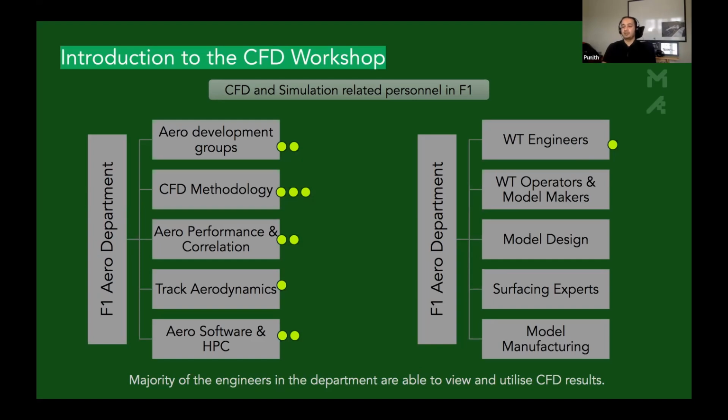They keep automating a lot of that as well, so that as you do one run in the wind tunnel, you get an incredible amount of data at your disposal, and then you can specify even more. You can ask for PIV, you can look for total pressure rakes, and then you've got 15 minutes, 10 minutes to analyze all that while somebody is changing a part before the next run goes.